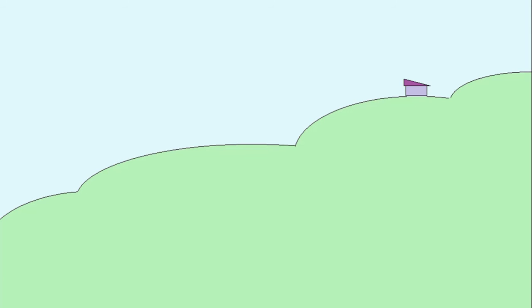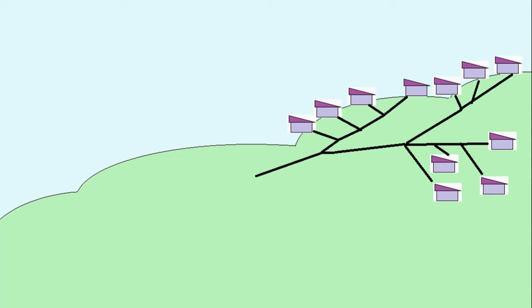The water you empty into your drains travels underground via a branched network of pipes that resembles your bronchial tubes. For the most part, gravity propels sewage through the pipes. As we'll see, gravity is harnessed several times throughout this whole process. Inevitably, the sewerage pipes reach an elevation too low to be useful. At these points, lifting stations are installed. Inside the lifting stations, sewerage is moved vertically by pumps, from which point it can continue its downward slide.